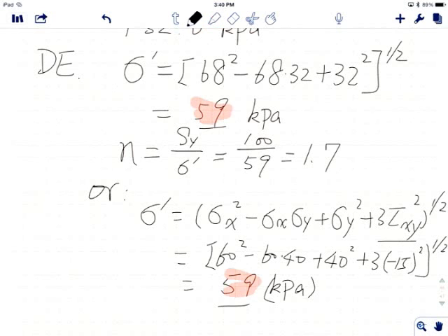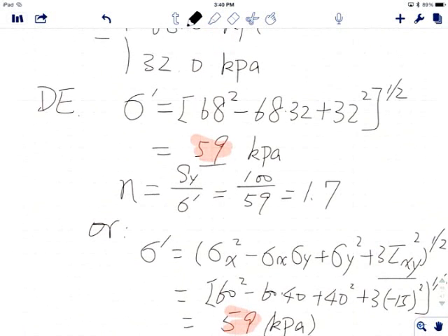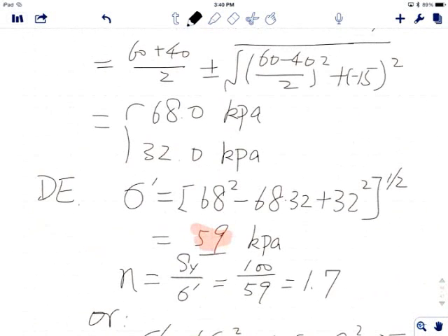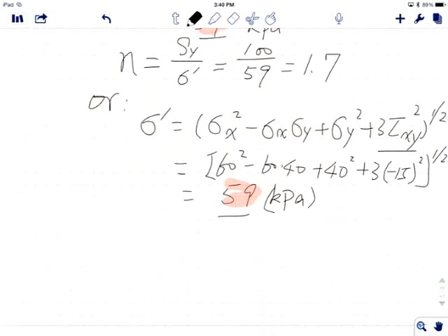So in other words, when you have both normal stress and shear stress and you want to calculate the von Mises stress using distortion energy, you can do it two ways. First, find the principal stress, like I did here, and plug it in, with no shear component. Or you can just use this definition with the shear stress and plug it in. It gives you the same von Mises stress whichever way you do it.